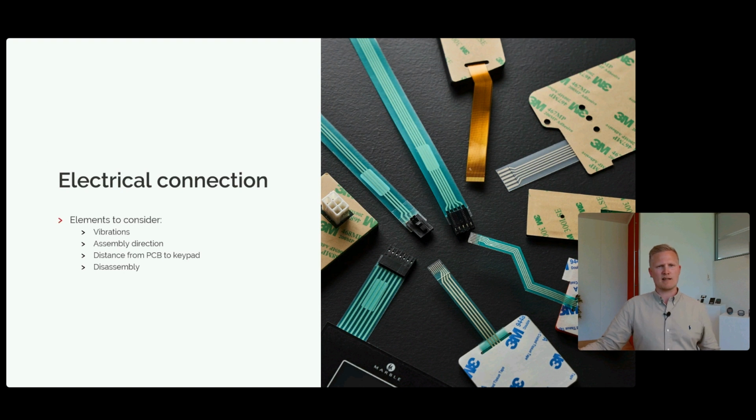Is it going to be disassembled? Do you need to consider how you should disassemble the tail from your PCB? The most common and cost-effective interface between a keypad and a customer PCB is a tail made to integrate with a ZIF connector, like shown here.